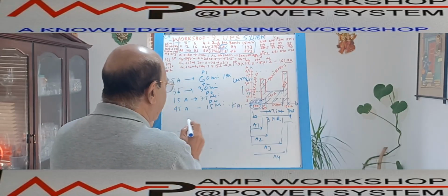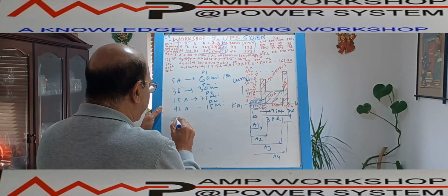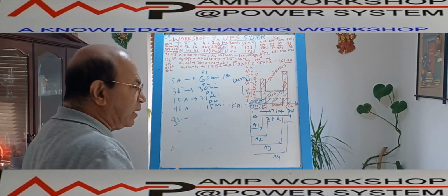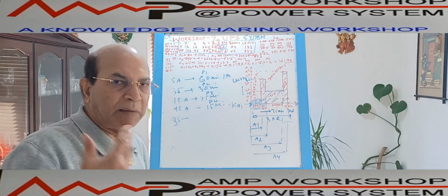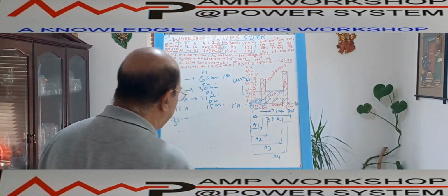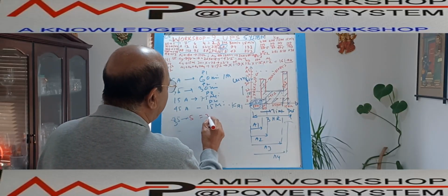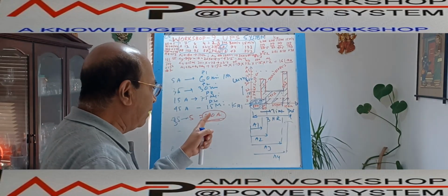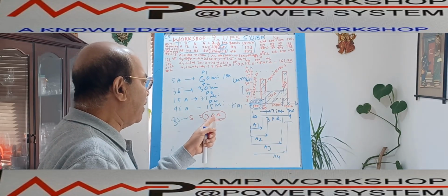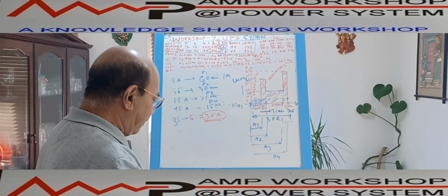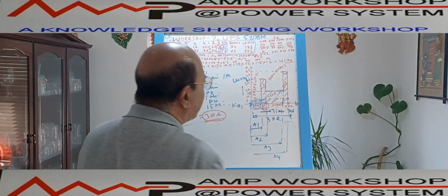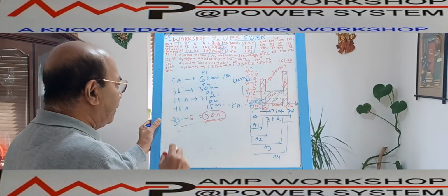So in the second part, our total current is 35 ampere. But when it is delivering 35 ampere, what is the battery condition at that time? The battery was already supplying 5 ampere current. So how much additional current is it supplying? 35 minus 5 is 30 ampere. So we have to calculate with this 30 ampere. When we calculate the ampere hour, we have to calculate it in terms of 30 ampere. And when we calculate the K factor, we will calculate it in terms of 30 minutes. And that is the second part.